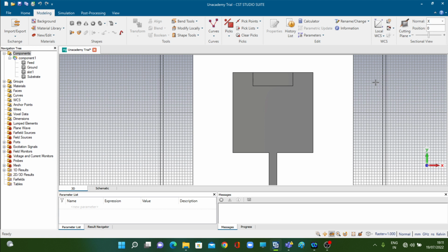Now I am drawing a one-to-one correlation: if you want to increase the bandwidth, you have to increase the path length of this current, which is popularly known as the electrical path length of the surface current. Electrical path length of the surface current. Now there is a problem in this.